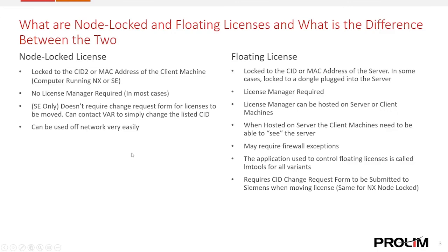Now, the first thing I'm going to talk about are node-locked and floating licenses and what the difference is between the two of them. I'm just going to go through each one individually first. Node-lock licensing is licensing that is tied specifically to your client machine. So this license is tied to either the CID2 in the case of Solid Edge or the MAC address in the case of NX, to your client-side machine, being the machine that is running Solid Edge or NX.